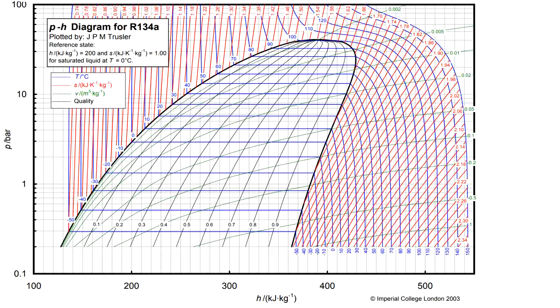Then the blue lines are isotherms. You can see that in subcooled liquid they are very steep. Then in the liquid vapor mixture they are horizontal lines because the evaporation or condensation would take place at constant pressure, and also at constant temperature, unless it would be a mixture of refrigerants with different boiling points.